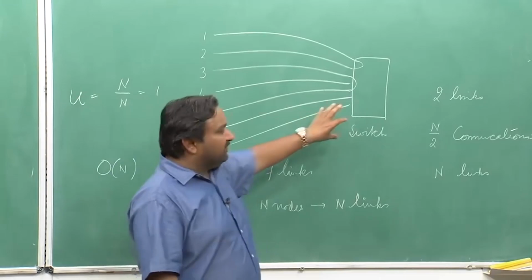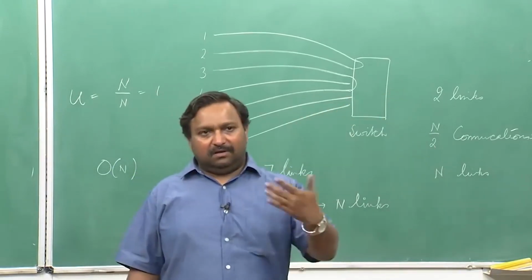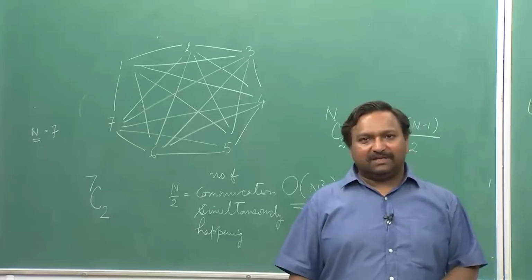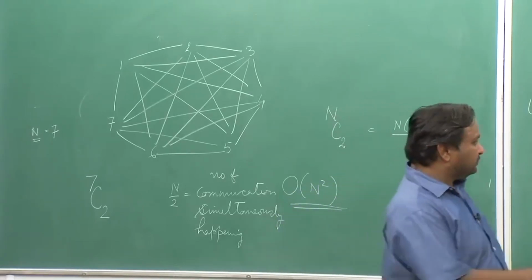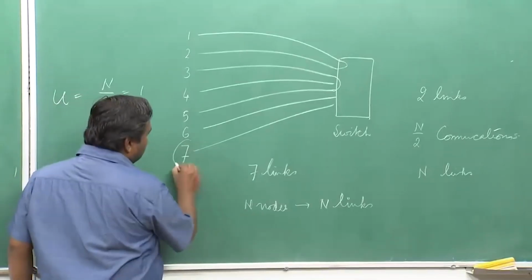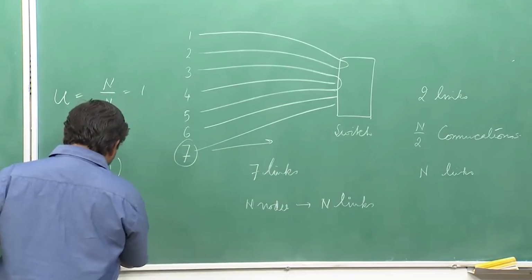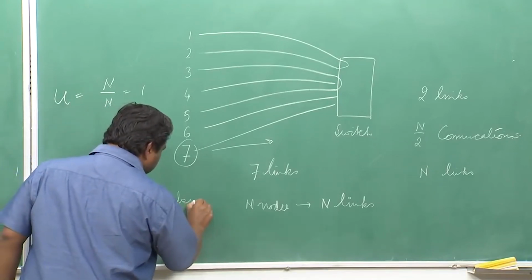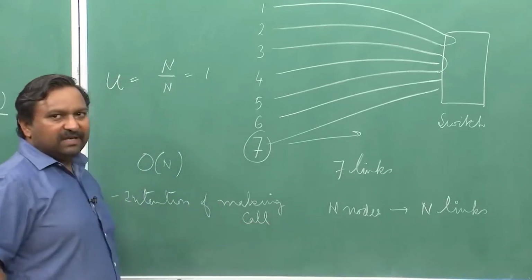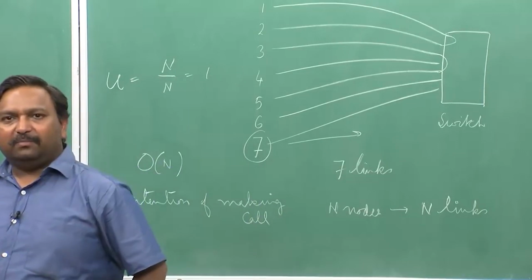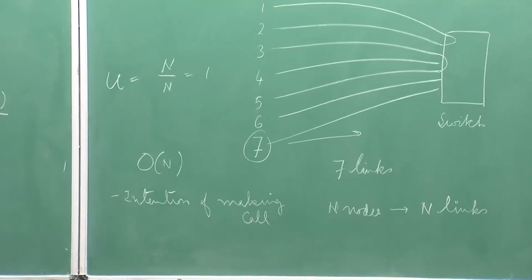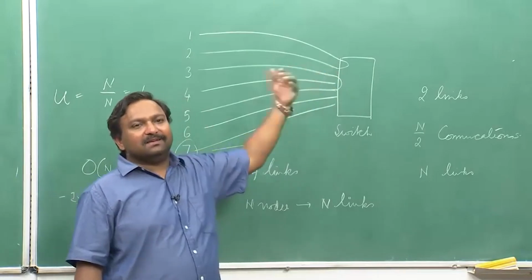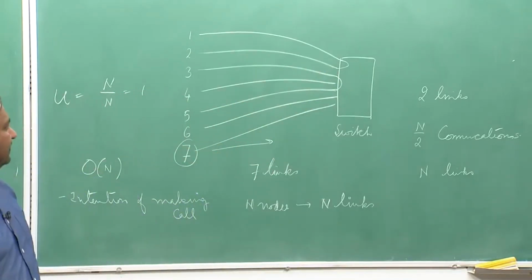In this case we have introduced something called signaling. I will talk about how signaling actually happens, with an example in manual telephony, and exactly the same thing that happens in manual telephony will be replicated in the electronics domain also. So, you have to first of all show, for example, to the switch your intention of making the call, that is needed. The switch has to tell you back, yes, you can actually make a call. Once that confirmation happens, you have to tell to whom you want to call, which number. Once this information is there, it will set up that particular path, confirm back, and you will do the communication. That is extra overhead which now comes.